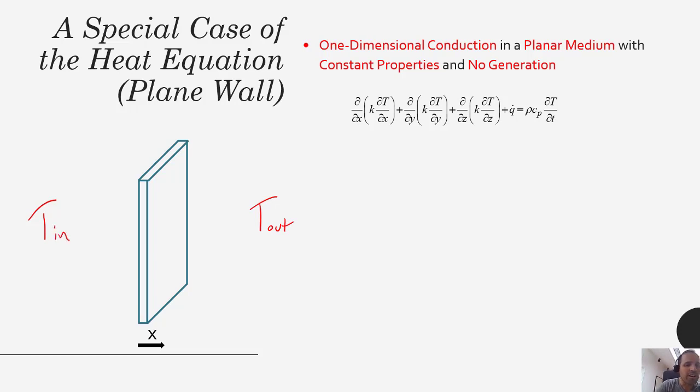So you might expect convection. You'd expect this air to be circulating reasonably well with the ventilation in your house and just natural buoyancy effects. Similarly for outside, you'd expect everything outside to be happening fairly uniformly and everything inside to be happening fairly uniformly. So that means if this is a larger wall, what's happening in the y direction or in the z direction, we can assume that those would be fairly uniform in those directions.